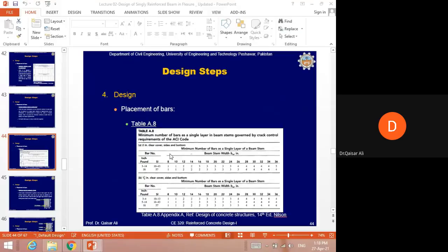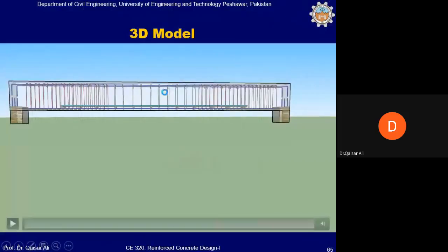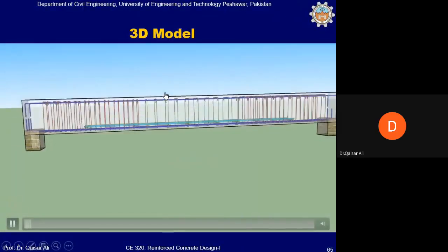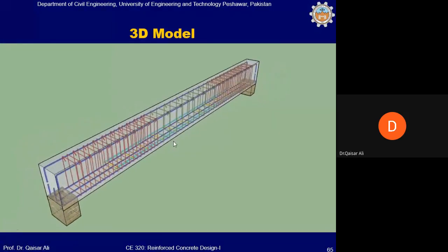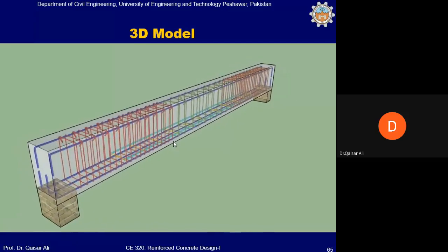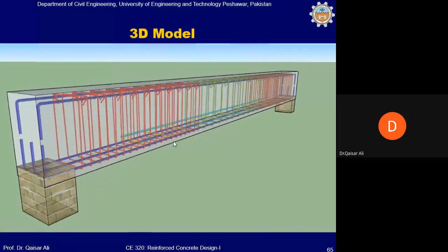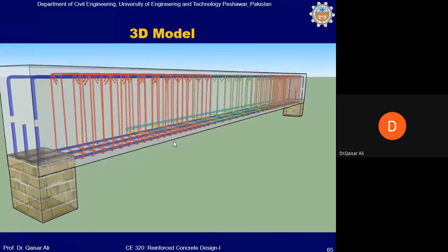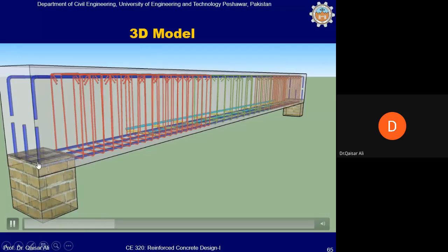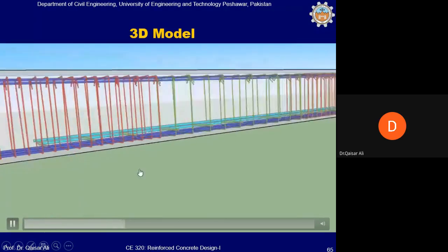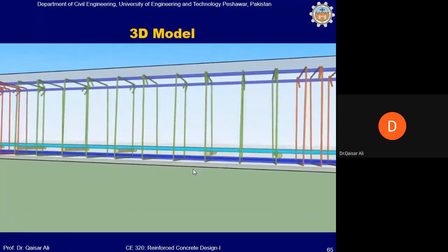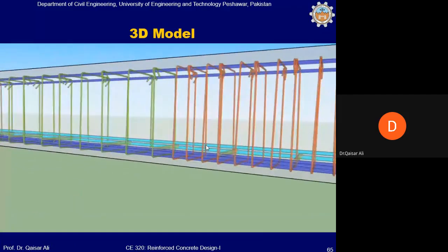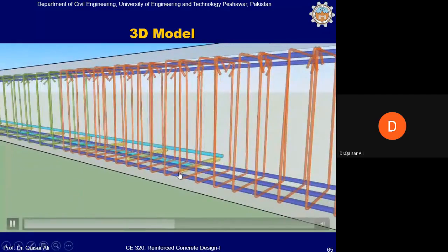Okay. Next, I will show you a video where you will be able to see actually the reinforcement in detail. You pay attention to the video and look at the reinforcement which is being placed. The bars have been carried to the far end of the support, to this point, 3 bars, and then the 2 bars have been curtailed. You can see these 2 bars, they're not carried to the support. I will explain the reason for this. These are the spacer bars. Spacer bars are also visible.